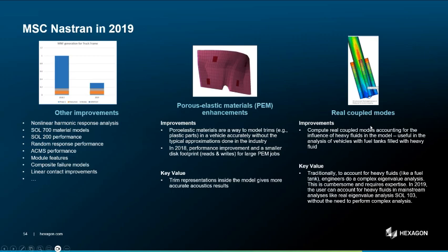It's also possible in Nastran, something that is not that clear. There's a couple of ways to model fluids in some kind of a simplified way. There's a virtual mass method, which is probably for large earthquake on something like a wall with water on one side, up to using the same acoustic theory, but then using that to model the elements inside and to model the fluid and how it sloshes. Yes, you heard correctly, it's possible to do sloshing using that, but it's linearized, meaning no large displacement, no splashing, and so on. You can, in a Sol 700 simulation, which is explicit dynamics, do a full sloshing simulation if you really want to. But this is a very efficient way to couple fluids and structures. So if you want analysis, do both.